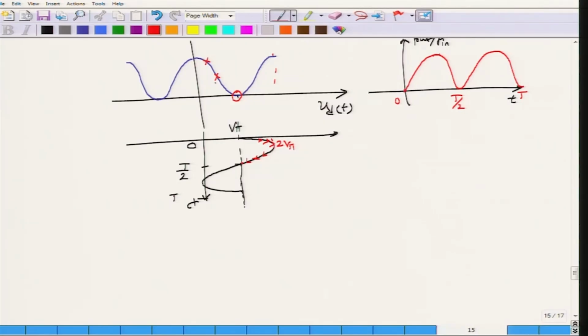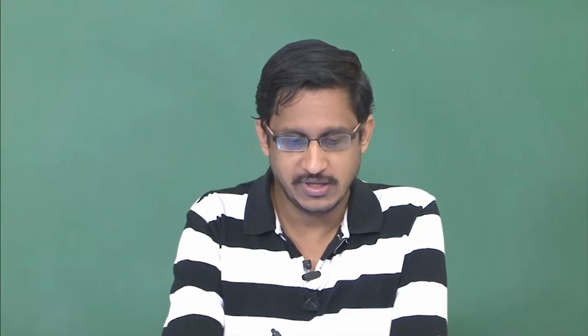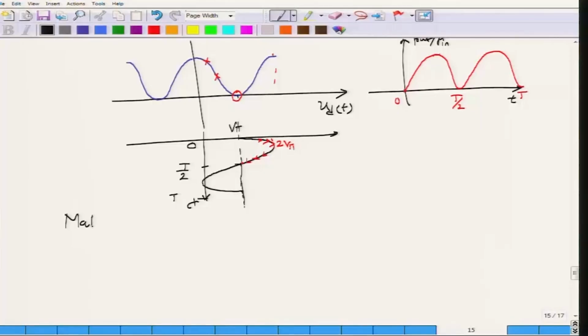In fact, you can send in any complicated signal and then find what would be the output of the Mach Zehnder modulator. You can do all that in simulation by using MATLAB and writing a simple program to give this as one input, write down the power transfer function of the Mach Zehnder modulator, and then find out what kind of pulse shape you are going to obtain.